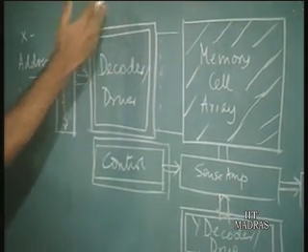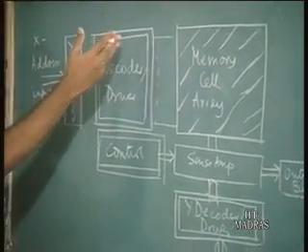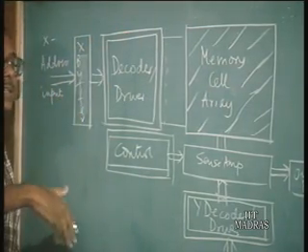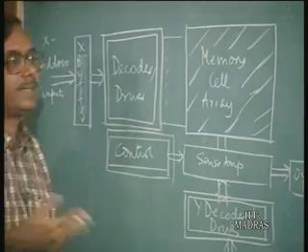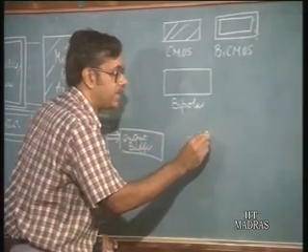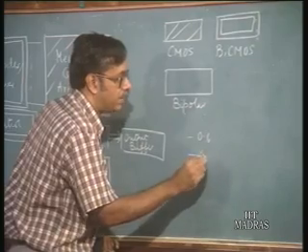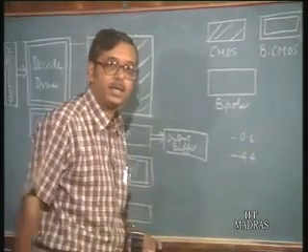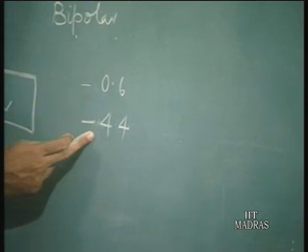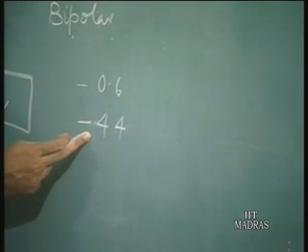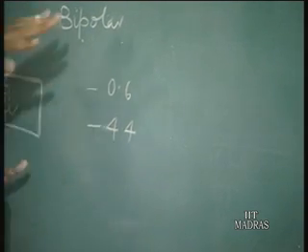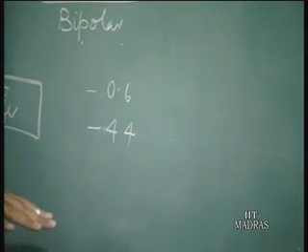So, if 0 is going to be VDD, you can represent 0 voltage as VDD, and you have minus VSS. So, in fact, the voltage levels internal to the circuit can be minus 0.6 to, say, minus 4.4. Okay. So, minus 0.6 is considered logic high, whereas minus 4.4 is considered logic low. So, basically the CMOS is going to operate in the same way. It is just a level shifting down to negative voltages.